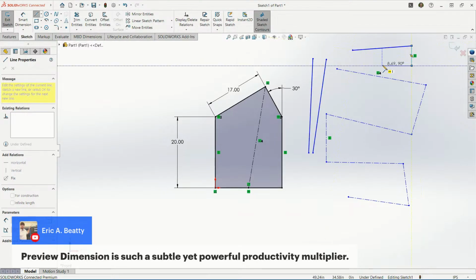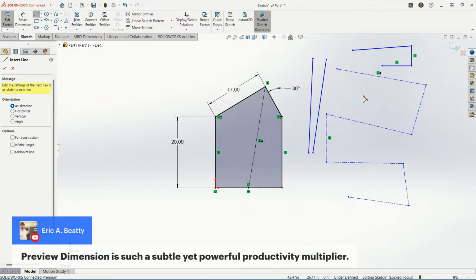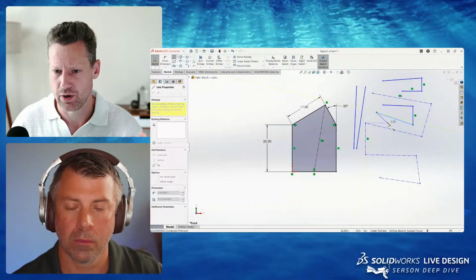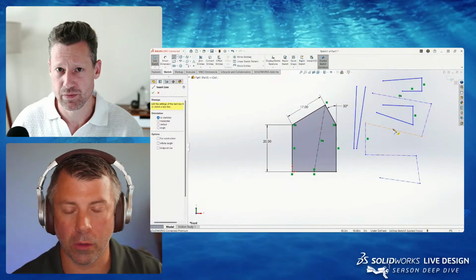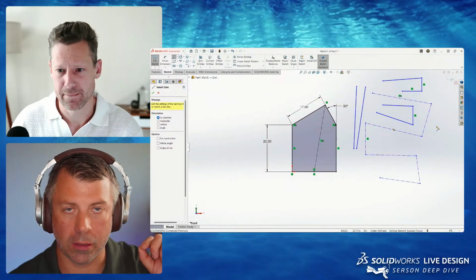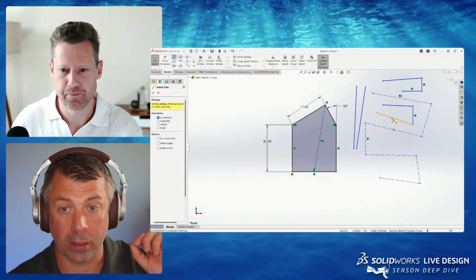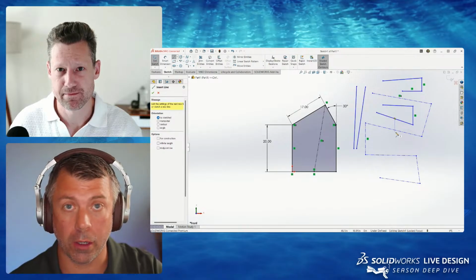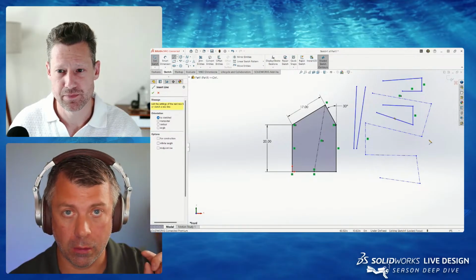Also, if you're in the click, click mechanic and you are done creating this set of lines, but want to create another one, you shouldn't hit Escape. You should actually just double click. And you'll still be in the line command, but now you're no longer attached to that previous line. And then you can go here, double click. Cool. So click, click, click to draw a continuous line. Yep. Click, drag to draw a single line, or whenever you want to stop drawing your line, double click.